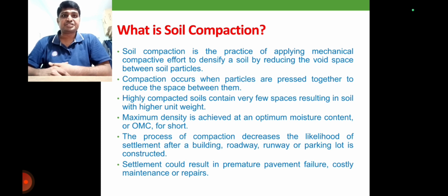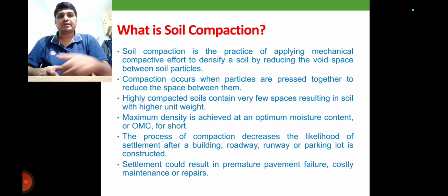Maximum density is achieved at the optimum moisture content, or OMC, for a short period. The process of compaction decreases the likelihood of settlement after a building, roadway, runway, or parking lot is constructed. The settlement could result in premature pavement failure, costly maintenance, or repairs.